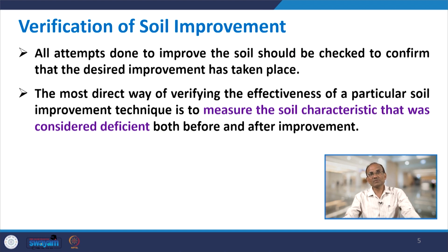Coming to the verification of soil improvement, all attempts made to improve the soil should be checked to confirm whether the desired improvement has taken place or not. We have a number of techniques for soil improvement, but it is not only desirable, it is a must that once you improve the soil, you confirm whether the improvement is enough or not. Many times there could be improvement in the shear strength and other things, but that may or may not be enough for the given requirement. So, it is a must to check.